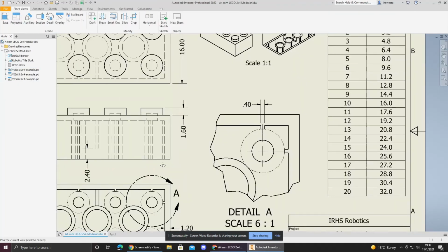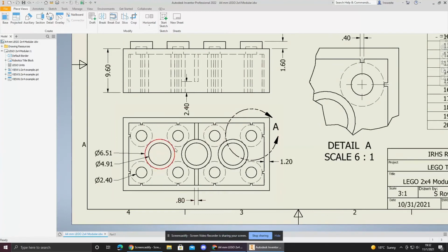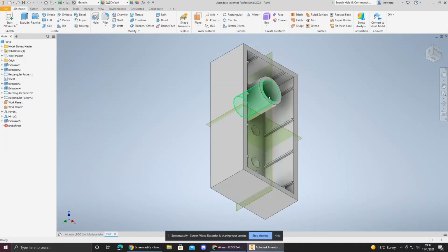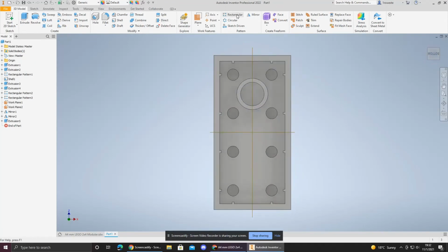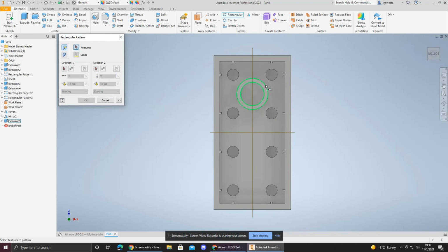Now, of course, there are 3 of these, but following suit with the current pattern, they're each 8 millimeters apart, so creating an additional one is unnecessary. We can instead, once again, use the rectangular pattern to simply translate them down the line 8 millimeters apart.